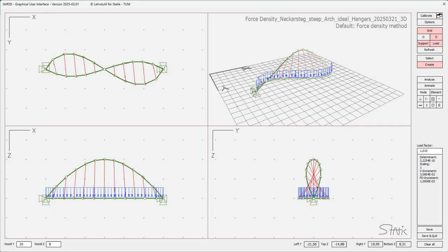This tutorial is about how to set up form finding problems with constraints on the coordinates of nodes, just the controlled position of these nodes. So we do this along this Schleicher-Bergermann and Partners benchmark with a pedestrian bridge, where we have an arch which is suspending the deck of this bridge.